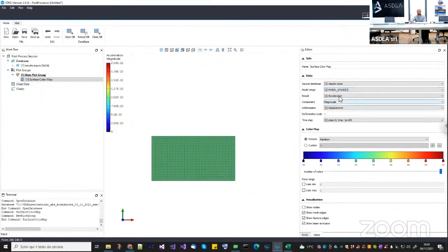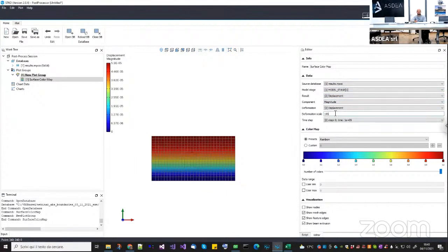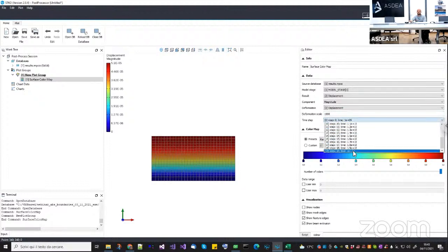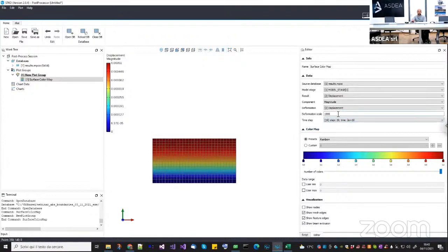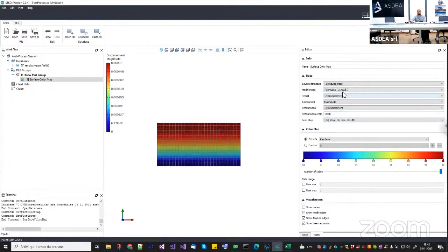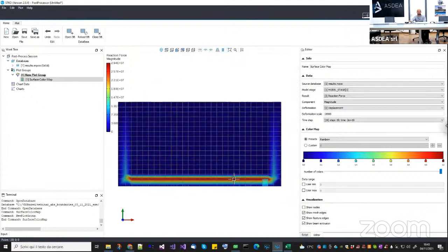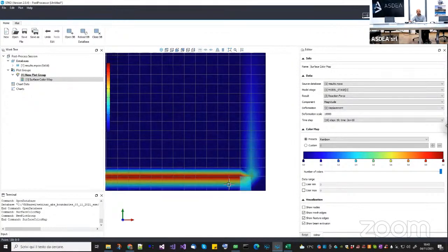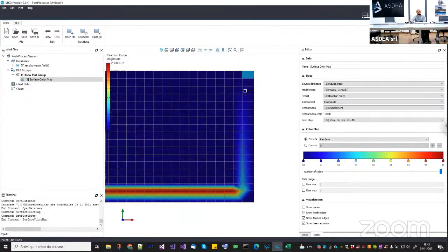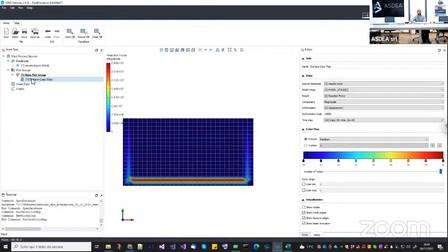First, in the first analysis, let's see the displacement field. So you have a vertical displacement. Here it is not moving that much. Of course, it was at the beginning. Let me go to the end of the first stage. This is the vertical displacement at the end of the first stage. If I try to visualize the reaction forces, you will see that they are automatically computed by this element. Of course, you will see the reaction only at the interface between the absorbing boundary and the soil domain. These are the reactions.